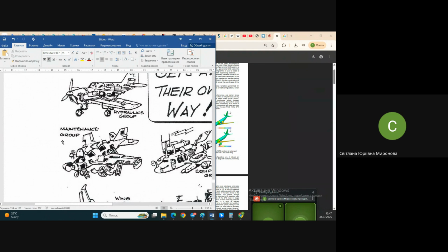If the regularity of the structure is broken, it's foiled, not complied, it means that you need to reinforce this place. Reinforcing this place results in increasing the weight of the structure of the airplane. Increasing the weight results in increasing fuel for each flight. I've maybe already perforated your brains with those stories. I need you to remember this permanently, keep it in mind.